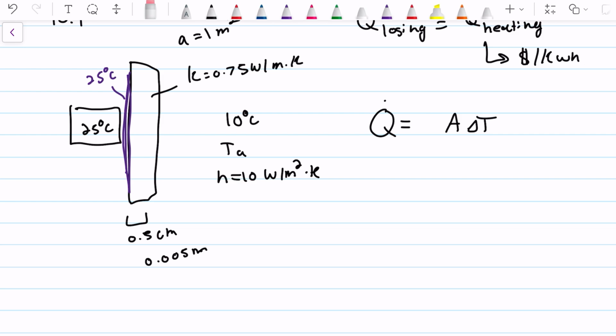Or actually, since we're going to do this with overall heat transfer coefficients. So basically, if we look at the gist of the temperature profile for a problem like this, since this is fixed at 25 degrees Celsius, this is known. We know in a solid it's linear. The temperature profile would look like that. And then with ambient, if it's 10 degrees Celsius out there or something, it would drop like that. Perhaps that was extreme. Maybe something like that.